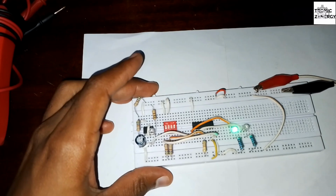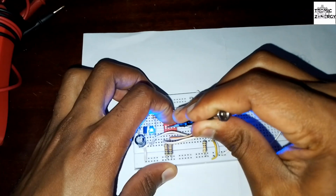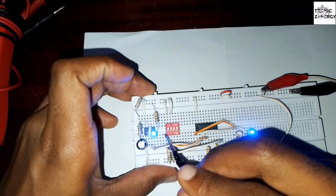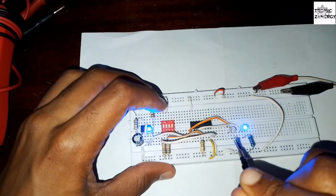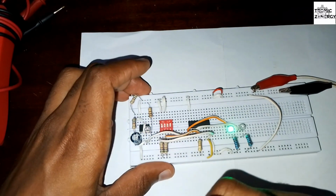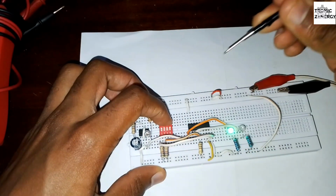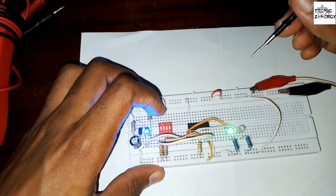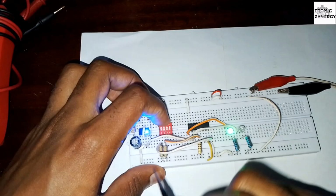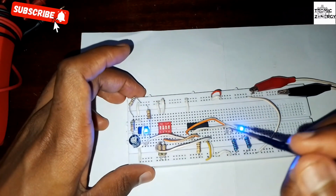So it still works the same. Let me turn it off. Yeah, like that. So it still works the same. When I turn this J switch on, it's going to turn on the green LED, meaning that we are feeding data. And when I turn it off, nothing happens until I press the K input, which is when it's going to turn the blue LED on, like that. So that's basically how JK flip-flops work.